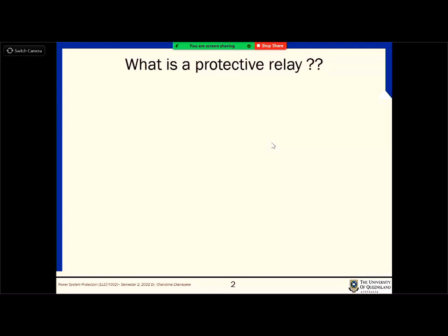And then the other thing is that not only defective, sometimes the system is behaving in abnormal ways. Sometimes it's not 100% defective, but say the voltage level suddenly, in a transformer, the tap setting is now off due to some reasons like, let's say, solar feeding or whatever, and now the voltage level goes up a little bit, right?